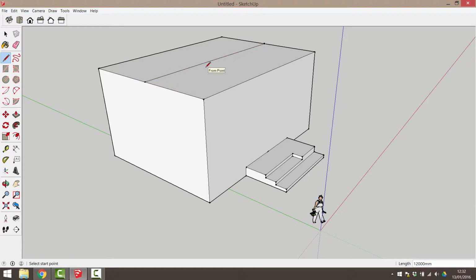To create a pitch, we'll move this line upward. Before we can move it, we need to select the line. Click on the black select arrow. Use this to click on the line just drawn. It turns blue to indicate that it has been selected. Now use the move tool. Click once to activate and to begin to drag.